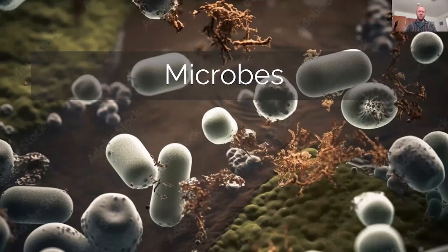And then also microbes. The composition of what microbes are in that water, they may like to stick together more, or they may like to push apart more. And this variable is more so in the secondary clarification, having to do with sludge age. But just know that particles or microbes are interacting with themselves, with other bacteria and particles throughout the whole process. So it can help with that flocculation.